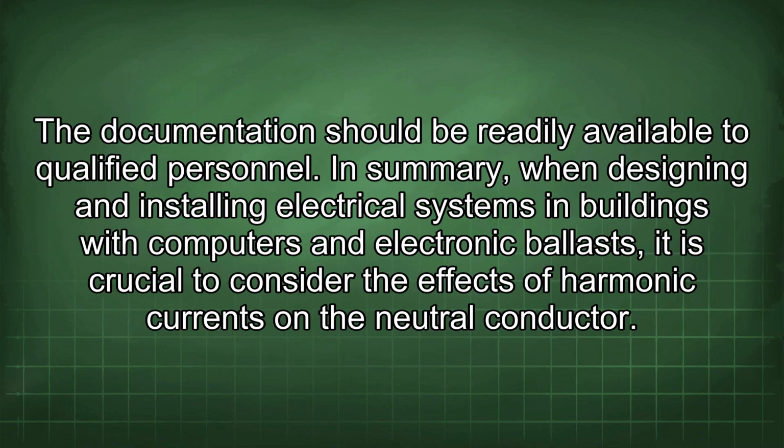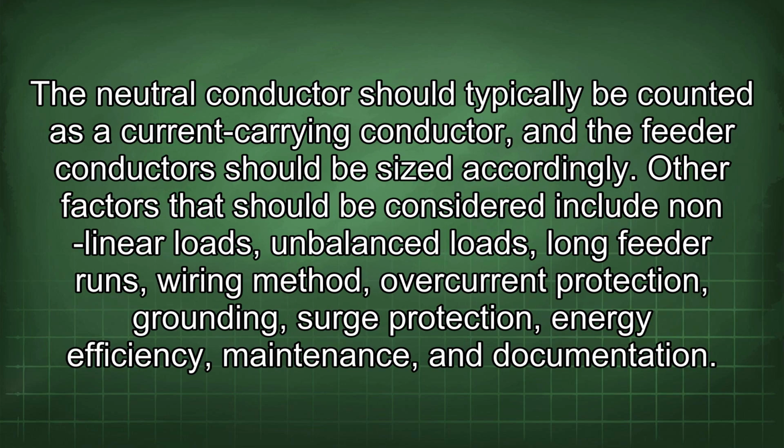The documentation should be readily available to qualified personnel. In summary, when designing and installing electrical systems in buildings with computers and electronic ballasts, it is crucial to consider the effects of harmonic currents on the neutral conductor. The neutral conductor should typically be counted as a current-carrying conductor, and the feeder conductors should be sized accordingly.